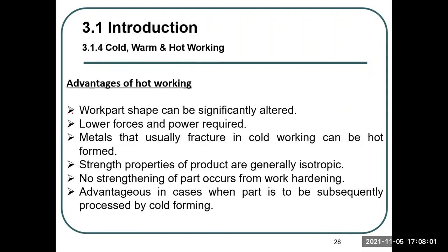Since ductility is increased, you're going to have all kinds of shapes, with lower power and lower force. If the material fractures very easily in cold work, you cannot use cold work, and you can only use hot work. Sometimes, after hot work, people still want to increase the strength, so you can still do a little bit of cold work forming later. The good thing about hot work is you can get all sorts of shapes compared with cold work.